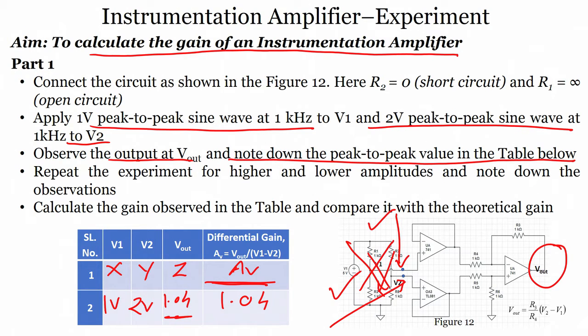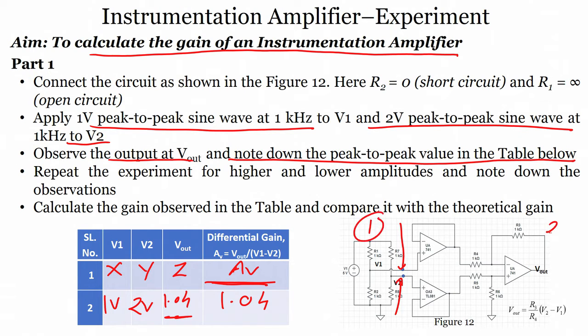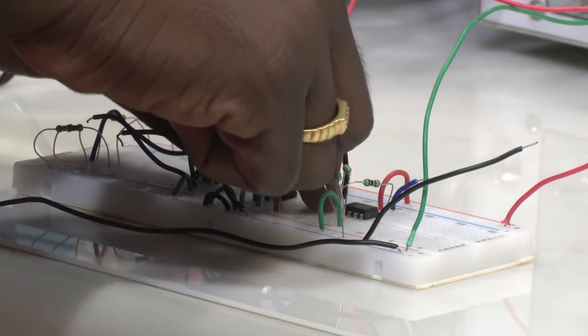Now, what will happen if I directly connect the potential divider output and see what is the voltage difference between V1 and V2. So, if I measure voltage here, first I will measure voltage here, and then second I will measure voltage at V out, alright. So, first I am measuring the voltage at the output of the Wheatstone bridge. So, I have to apply voltage across the Wheatstone bridge, and if the Wheatstone bridge is properly tuned, then my output voltage would be 0, right.